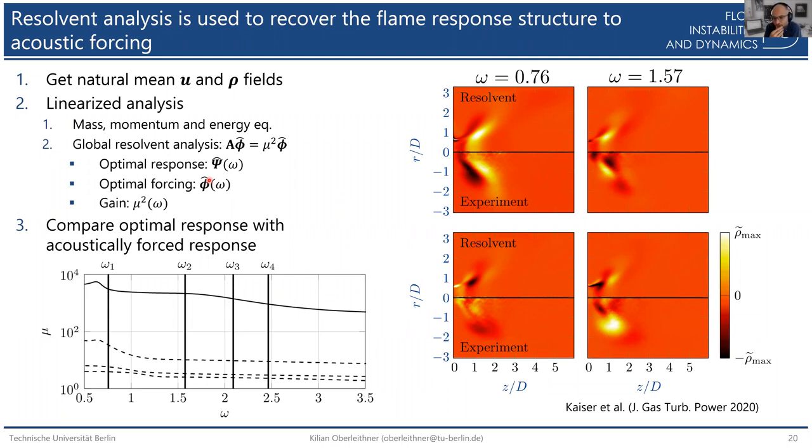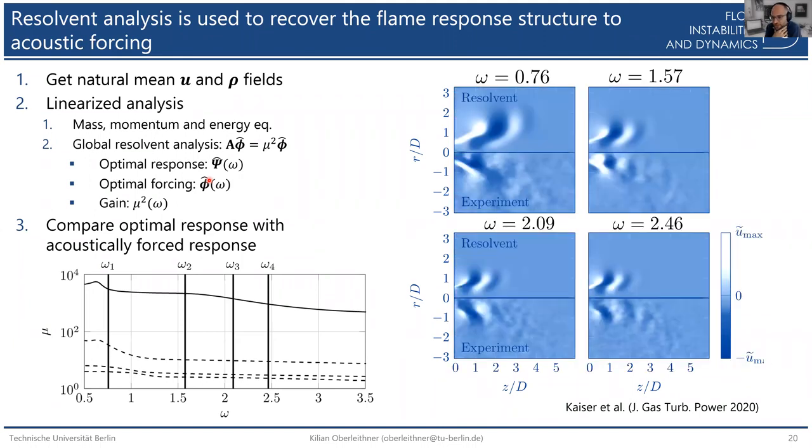However, I think you can basically take two conclusions from this work. First, for low frequencies, your model here seems to work, and you do not need to include any chemistry model to predict the flame response from a linearized analysis. And second, if we consider the flow response here, which seems to match for the entire frequency range, it seems like the resolvent analysis, which represents the most optimal structures with respect to stochastic forcing, is quite similar to our flow response to acoustic perturbations.